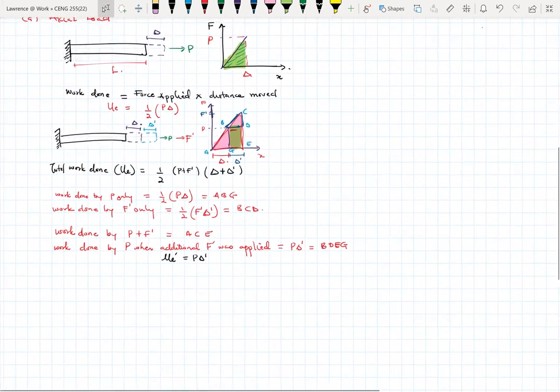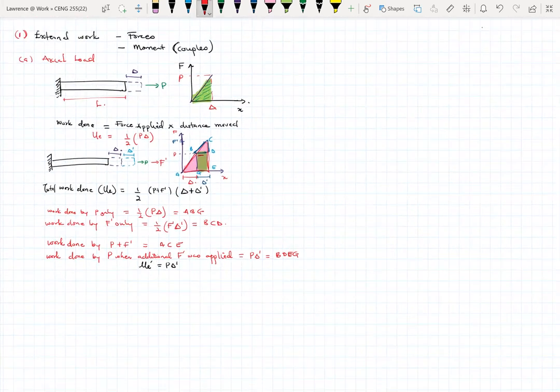I'm just sidetracking. When you were looking at basic structures, I think your focus was on the trusses. One thing you learned about trusses is that they are axial members. They have no resistance with respect to shear and bending. So the individual members in the truss transmit loads through axial action. That's the reason why we are starting with the axial forces, because we need this information along the line to formulate equations for axial behavior of trusses.